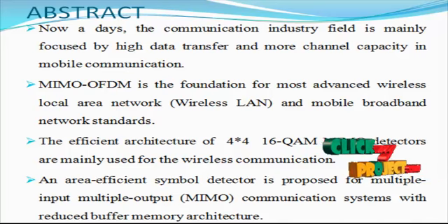and 500 Mbps respectively. SC-FDMA utilizes a discrete Fourier transform spread OFDM modulation with similar performance compared to OFDM. Its main advantage is to provide a lower peak to average power ratio, which makes the technology the choice for the uplink. However, the implementation of the MIMO detector in the SC-FDMA system is significantly more complicated than in the OFDMA system.